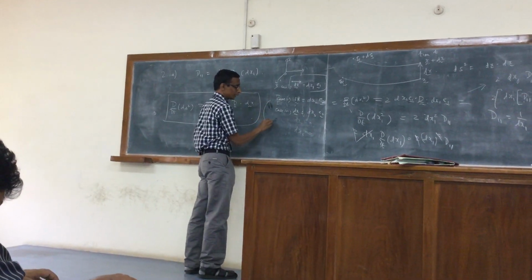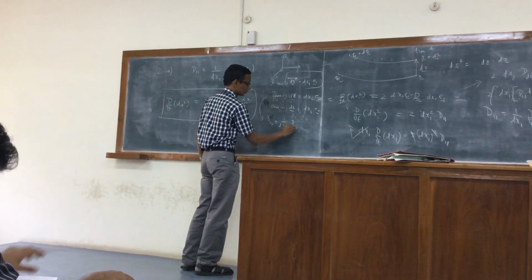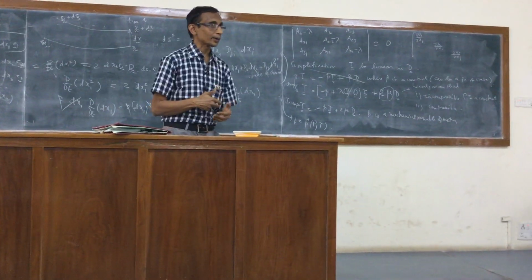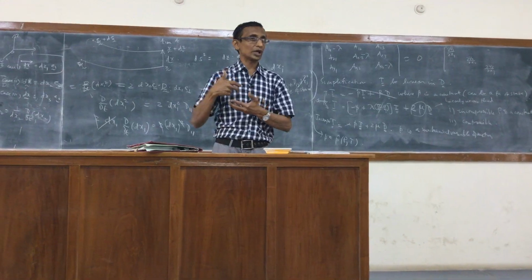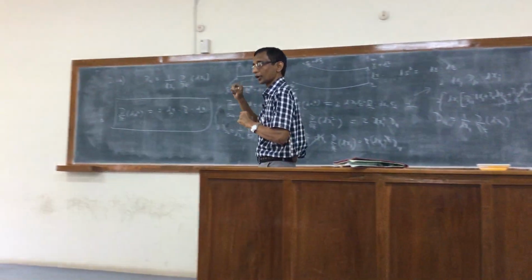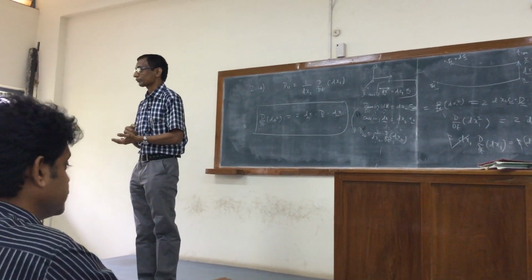Clearly, this would lead to D22 being 1 over dx2, and so on. So D11 can be regarded as the time rate of change of the length of a fluid element that is oriented along the O1 direction per unit length of that element.